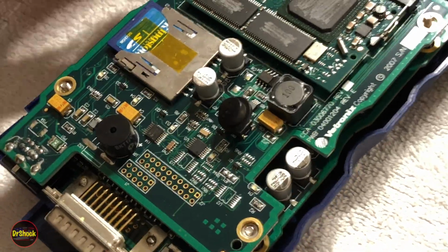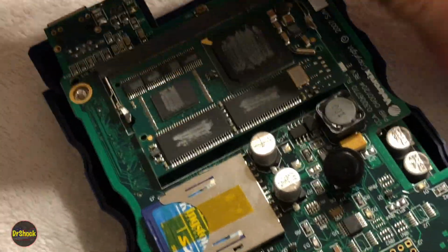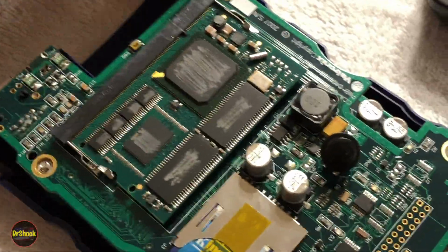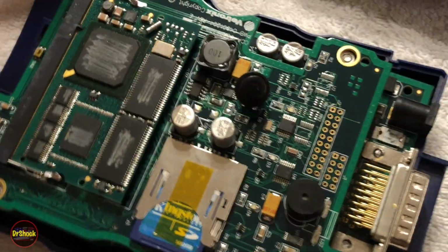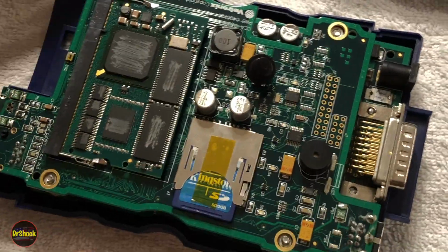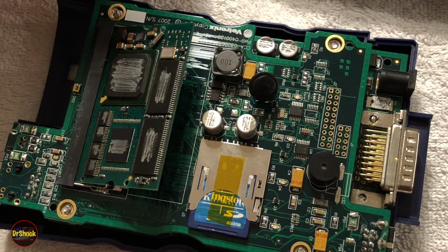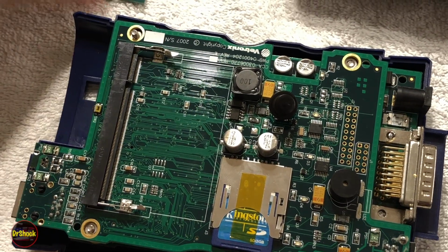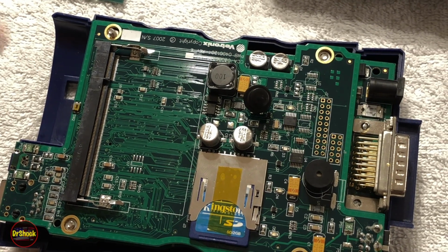All right, so what do we think the problem is with this guy? Well, this guy said it was an FPGA type error. Let me tell you, I ran that test a couple of times and I get different results. Sometimes I get the UART failing and sometimes I get the FPGA failing. So the first thing we're going to try is take this CPU daughter board, or this MCU daughter board, out, and swap it with a known good one to confirm the diagnosis here.